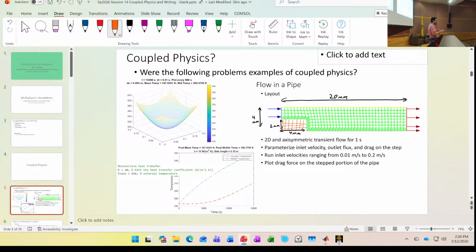Now, if there's deflection, what happens to flow over the step? If that step changes shape, is that going to affect the flow? You betcha, right? So technically what you would want to do then is rerun and calculate the new flow based on that new geometry. Calculate the forces again on that solid, soft region. See how it deflects. Maybe it deflects a little bit differently than what you calculated the first time.